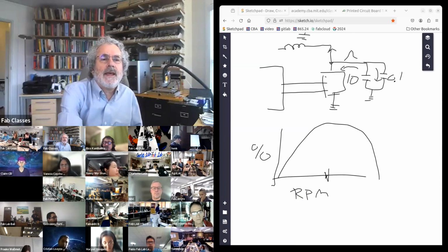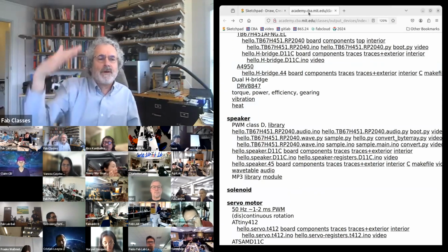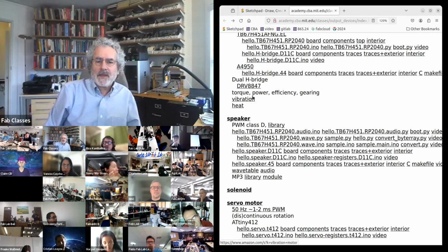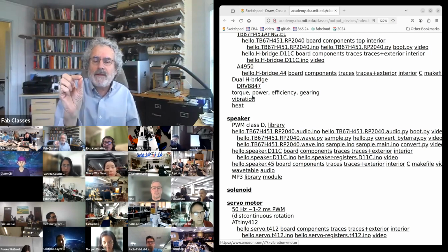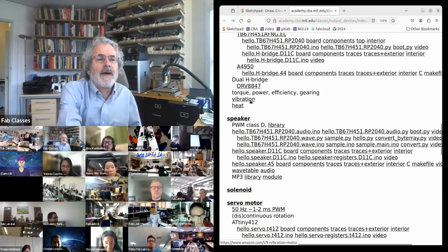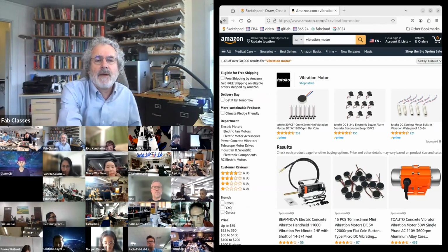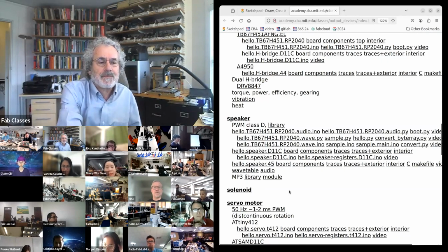So if you want a DC motor to turn slowly, you use what's called a gearhead motor that gears it down. And you can buy tiny DC motors that have a little weight on them that's unbalanced. And that's, if you want to get haptic feedback, you drive little tiny DC motors that have an unbalanced weight and they vibrate. Okay, need to keep moving.